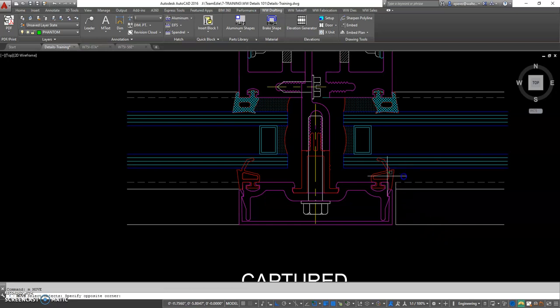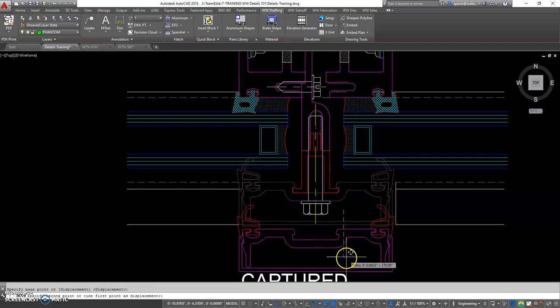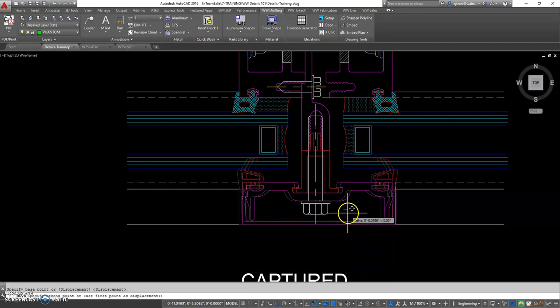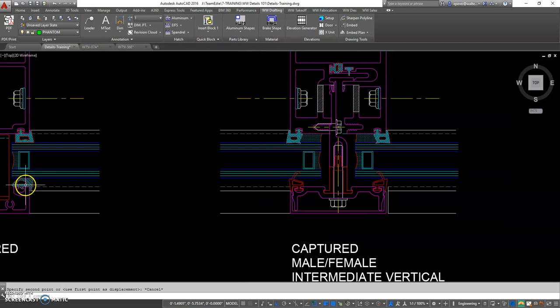So they use these wiper gaskets, pushed inside this plate or this extrusion. When the shop installs it, it all comes together at once in this motion, and then those wipers literally compress. That's why we have a different design here than at the captured jams.